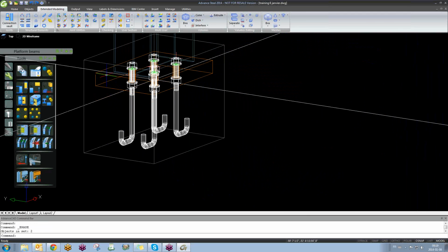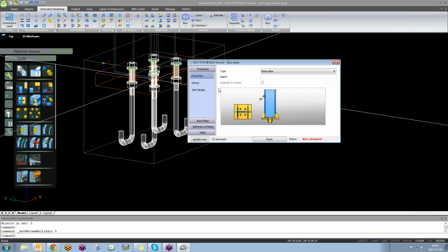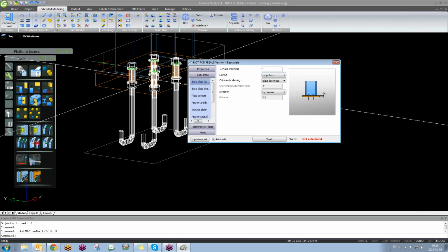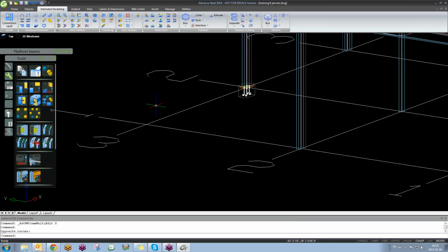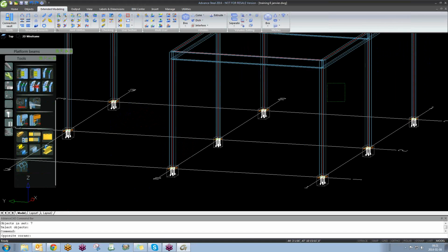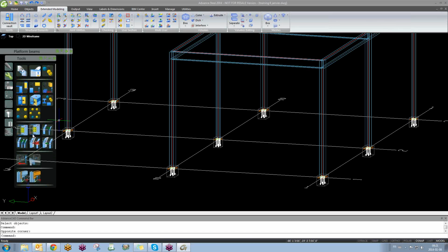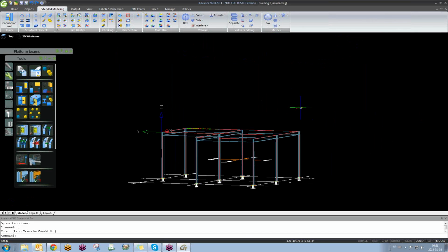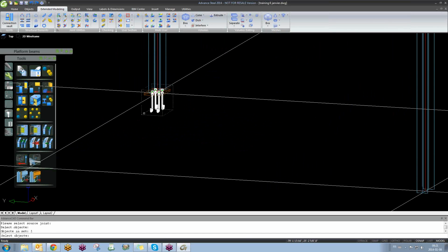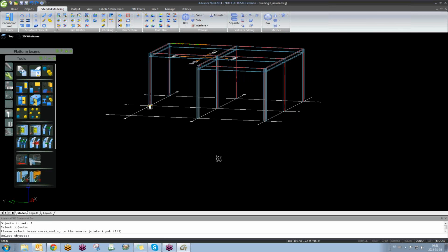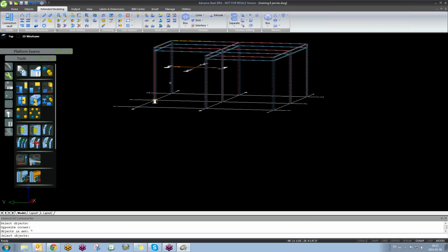Select the connection. Can you try it and let me know if it works? Exactly. Do you want me to show you that one more time? Let's just create multiple, right beside create by template. Okay, we'll do it again. Create by template multiple. Select any component, I will pick the intelligent box. Now just select all of them in one shot and hit enter.